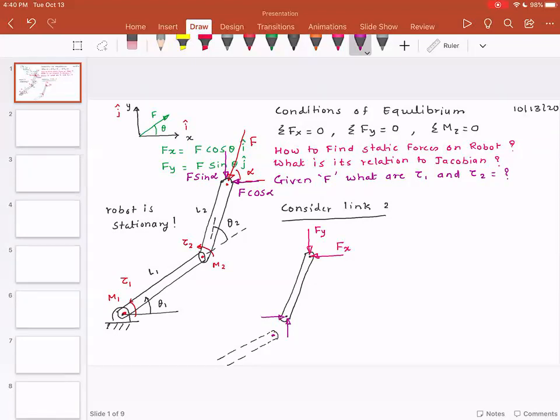These forces came into existence because for analysis, we broke the joint, which means equal and opposite forces act on this joint. So these are the reaction forces, and these equal and opposite forces act on this joint.